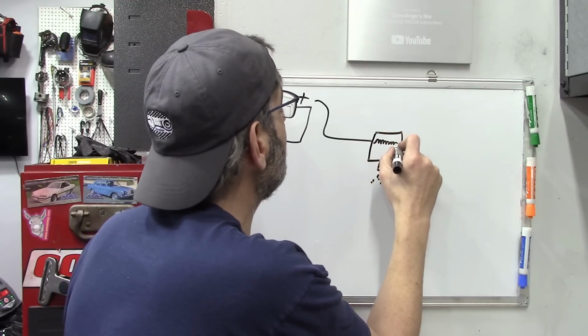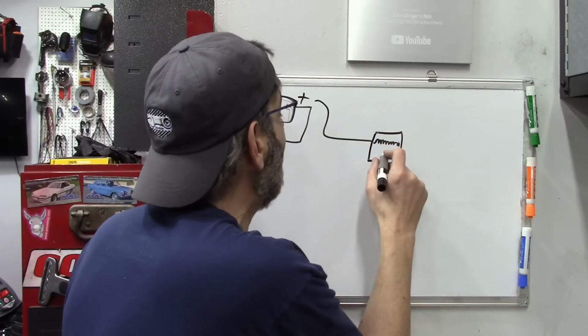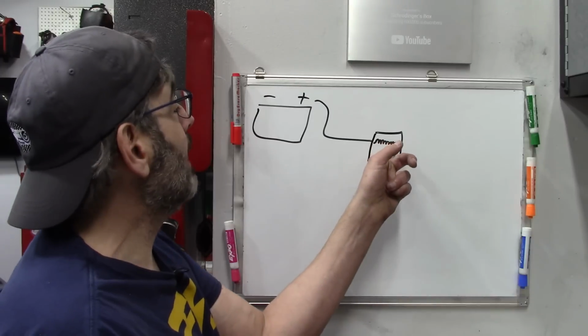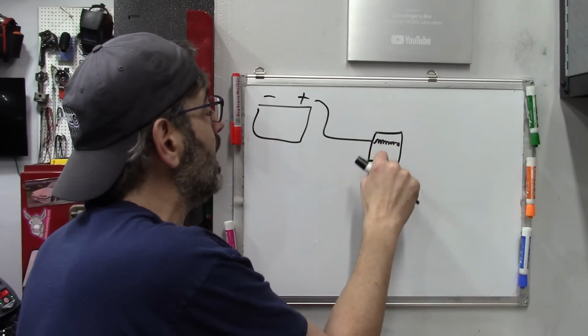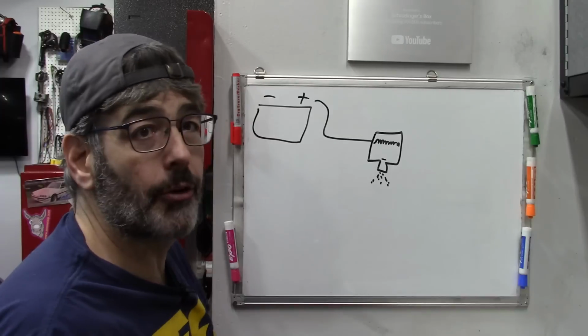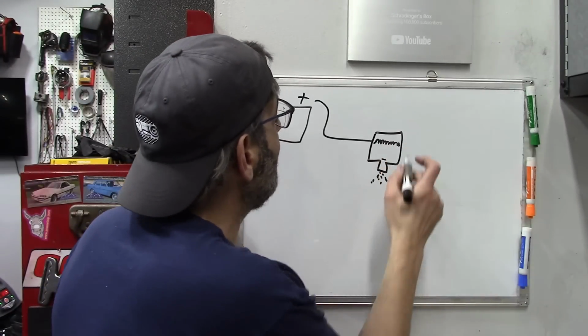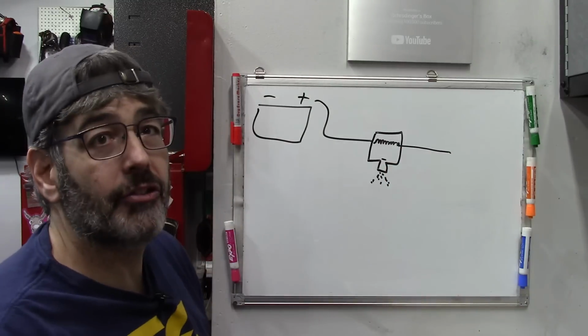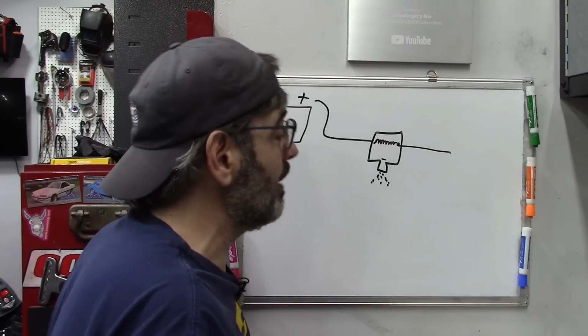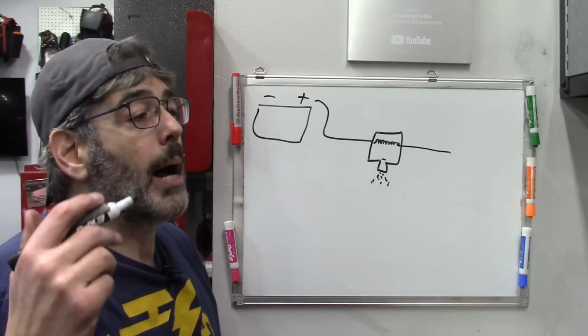Fuel injector is going to have a little coil. It's almost like a relay, actually. Solenoids are very similar like that, where there's going to be a magnet here and a little pintle here. By turning this magnet on and off, we open the pintle and close it, open, close, let fuel either go through or not. And we sort of pulse that through control of this magnet. Now, the control of this is, in every vehicle I have ever seen in my life, going to be ground side controlled. Did he use pull down? No, low side driver. Okay, so there are different terms for this: ground side controlled, low side controlled, pull down.